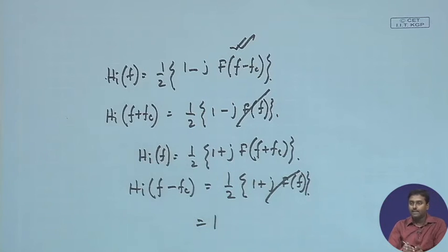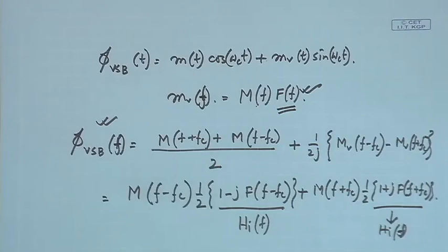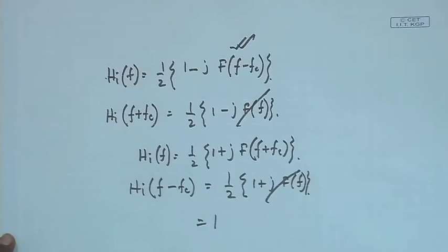If I just pass my signal through this filter, I will be getting the representation which is already proven for SSB-SC. I get almost similar representation for VSB-SC. So, that is why I can also see now things are all consistent. I can also see if I multiply this by 2 cos omega ct, immediately I get my signal back, because I multiplied by 2 cos omega ct, put a low pass filter, I will get my m(t) back. That is consistent. Earlier also we have proposed the same thing. So, we can see that with this particular thing we will always be getting this back, right.